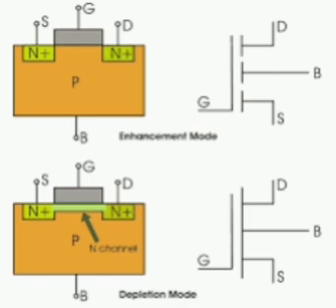Current in BJT: collector current in a transistor is given by IC equal to beta IB plus (beta plus 1) into ICO. IC equal to beta IB plus (beta plus 1) into ICO. This equation is valid in the active region. Beta means current gain of common emitter.